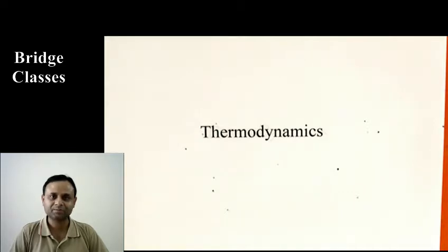And similarly, all gases behave as ideal gases under certain situations, which are low reduced pressure or high reduced temperature. Low PR and high TR, then they behave as ideal gases. So we get PV equals RT. And there are different forms of this law.